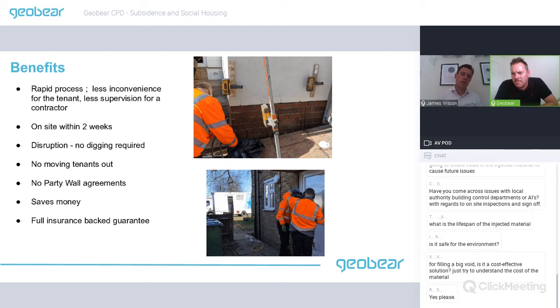That leads reasonably nicely into Richard's second question, which is what are the provisos when your system wouldn't work? So the bulk of the research that we've done, almost all the research and case studies, is on clays that have a plasticity of less than 40%. That would form part of our guarantee, that we would guarantee any work you do on clay that has a plasticity of 40 or less. Above 40, we can still provide a solution, we often do, but there's less research that we've done on those very highly shrinkable clays.